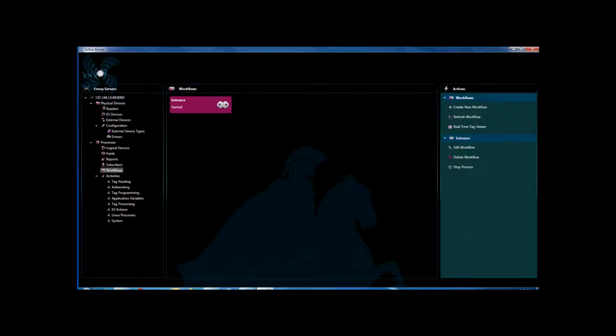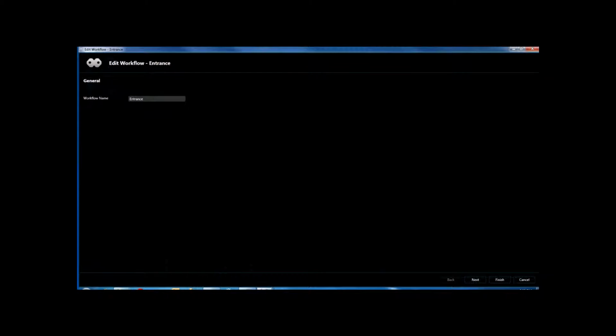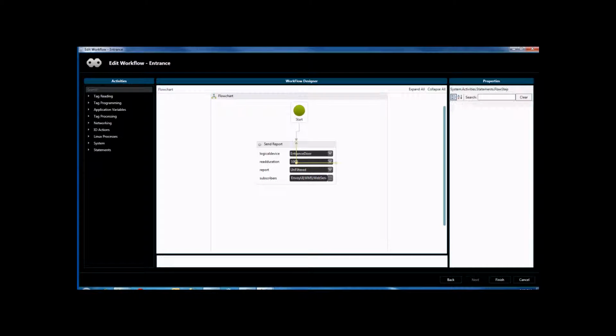Now, after this part is shown, we're going to edit our workflow so that we show the use of the start and stop triggers. If we go to the workflow section, on the start trigger I'm going to add a trigger. By default, it's only going to show me the input devices that are connected on the Envoy. I'm going to say that portal sensor 1 is to start the reading, and portal sensor 2 is to stop the reading. I'm going to choose values on so that when the portal sensor is triggered, the workflow will start and stop.